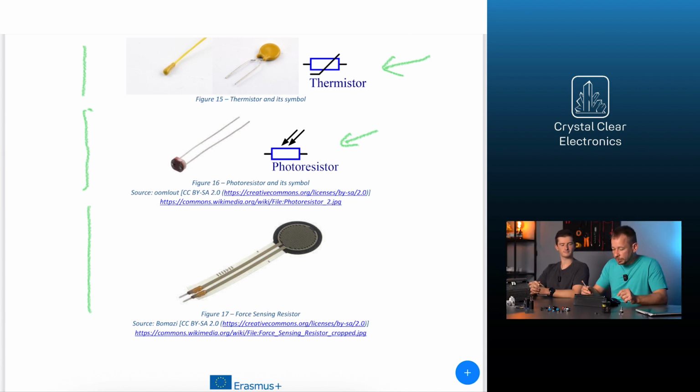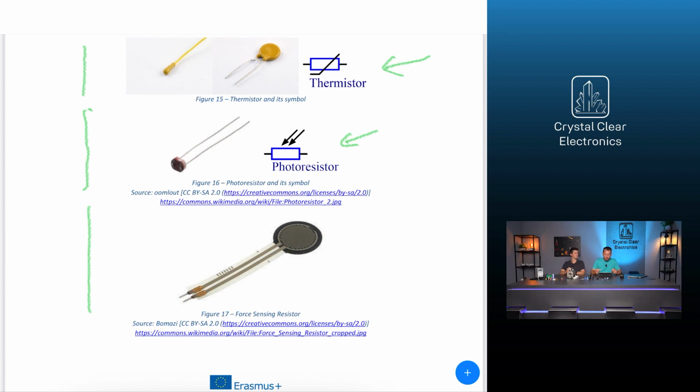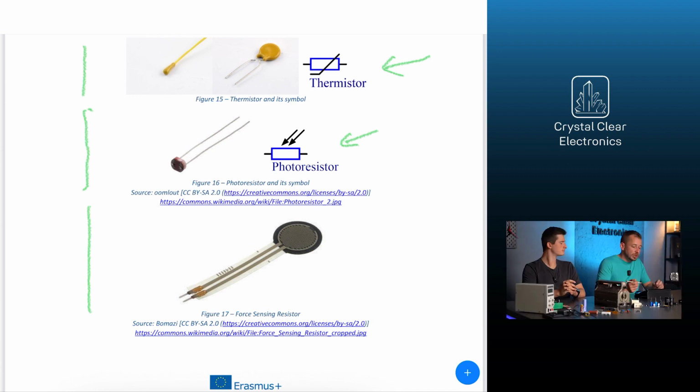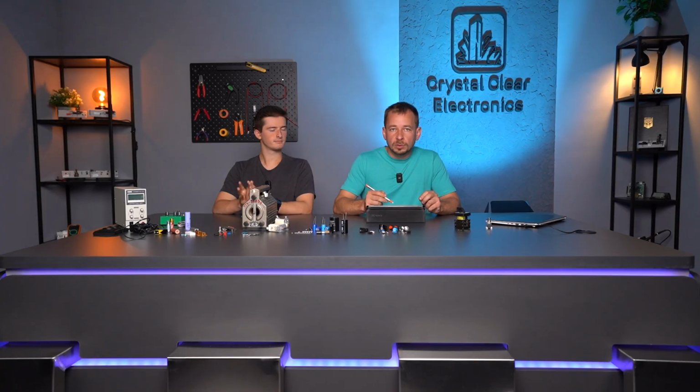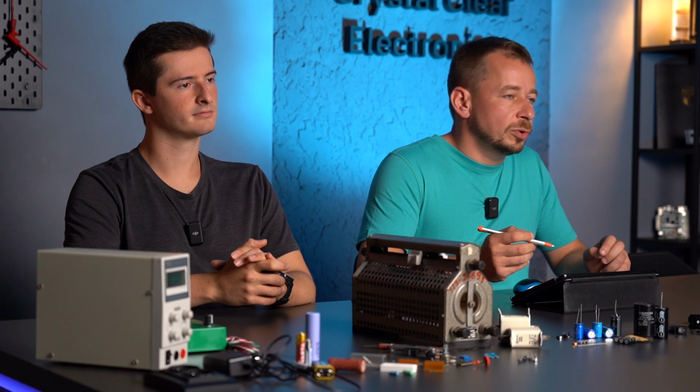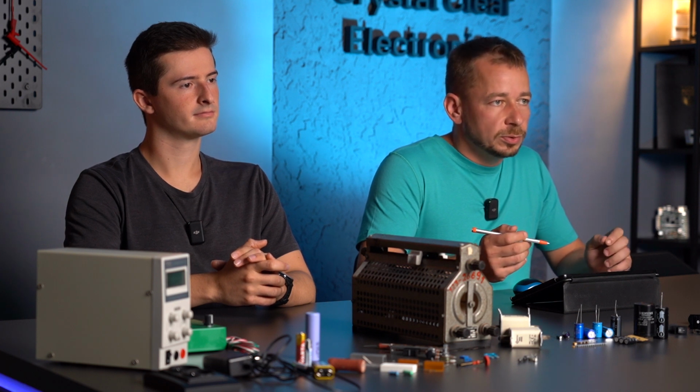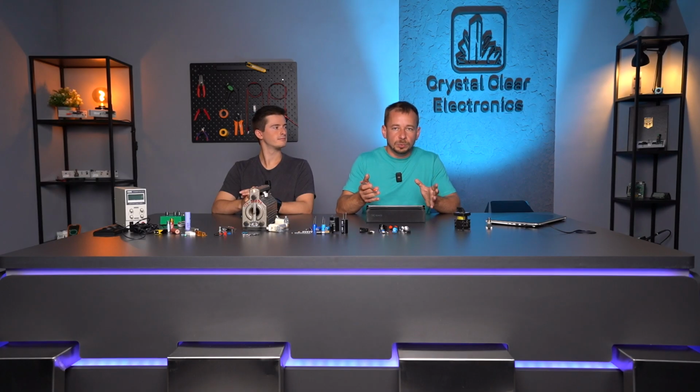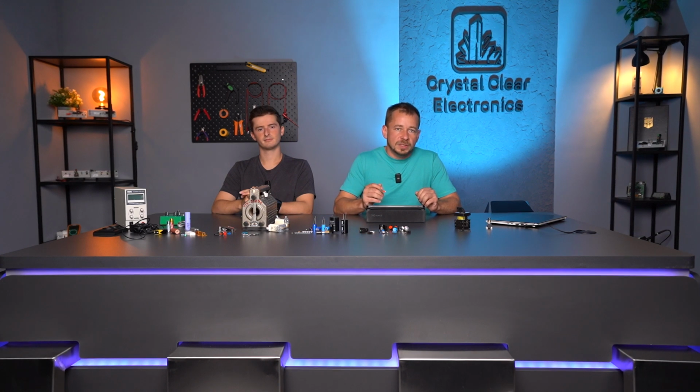If you attach a strain gauge to a body of known rigidity, you can measure the mass of, say, a giant industrial scale. A truck is placed on the industrial scale tray. The scale tray is held in the air by a few small pieces of steel on which strain gauges are attached. The elongation will be proportional to the mass, and so will the rate of change of resistance, and we can easily measure the resistance with our electronics. So we can measure the mass of the truck.